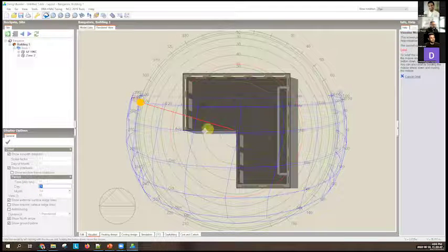Now, if you had one system doing this entire floor plate, then you can see here in the afternoon, these areas would receive direct sunlight. They would be quite warm. They would need a lot of cooling, right? The center zone won't. It needs cooling, but not as much as what you require in the perimeter zones.